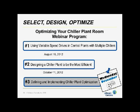Can we run the chiller at full load for a long period of time when we have another standby chiller available? Some people say it's not good to run at full load for a long period of time. I don't know of any reason why you can't run at full load or even above that for a long period of time. The main thing to be concerned about is not so much whether you're at full load, but are you at your high head. If your head gets too high and you start doing CPO algorithms that lower flow in the condenser, then you could literally put your chiller in surge. There's more consideration for that, but running at full load, it really shouldn't hurt your chiller if you ran that way forever.